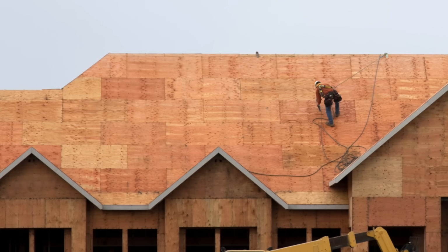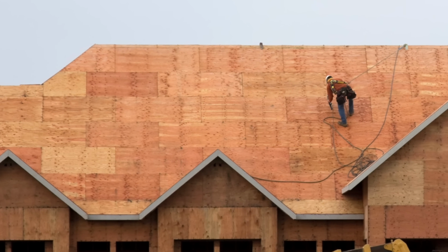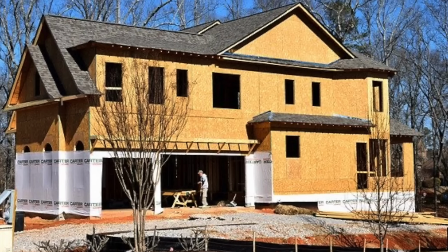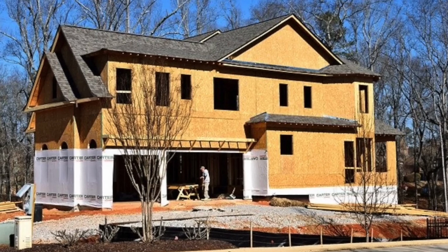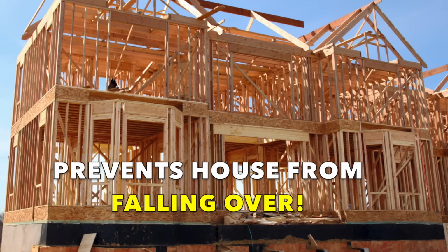But after all this framing is in place, our structure is essentially created. And yet, it's still not stable. Both the walls and the roof will still need to get sheeted or sheathed. Sheathing is a layer of plywood or strand board that covers the entire framing system from the outside like a skin. It's the layer beneath the house wrap and the siding. Sheathing is very important, and it often does more than just close the house in. It also prevents the house from falling over. But that's a topic for another time because it's complicated and it deserves at least one video of its own.